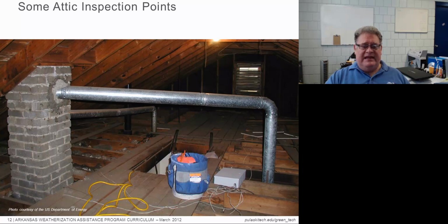And then our joist bay cavities. What about each of these? Are they prepared and ready to have insulation put in them? Is there trash under there that we're about to cover up? We don't want to leave trash. Speaking of which, look at all the sheetrock back over here, or what appears to be loose boards and sheetrock. We've got a gas line running over here. Okay, we may want to flag the connection points on that gas line, because gas lines are not forever. Plumbers do work on them. They do need to find them.